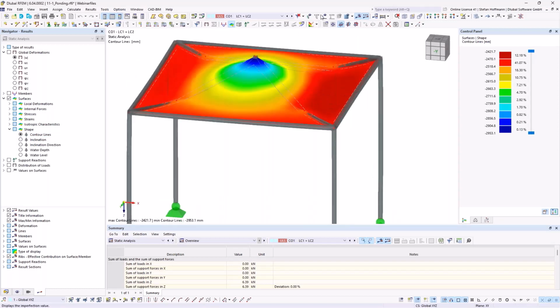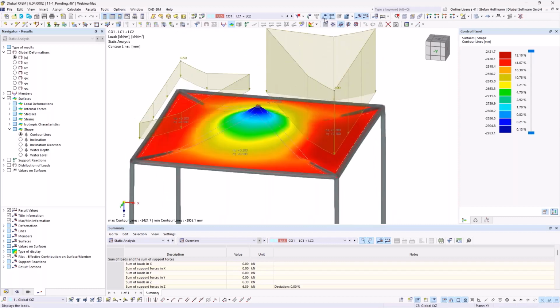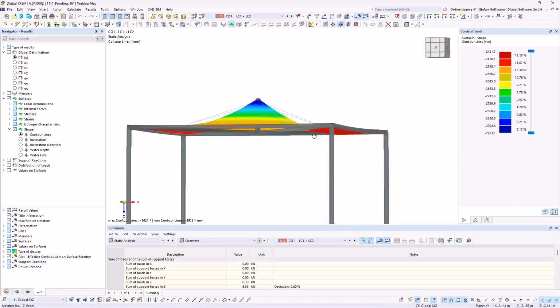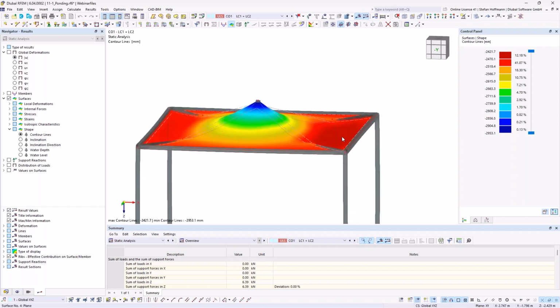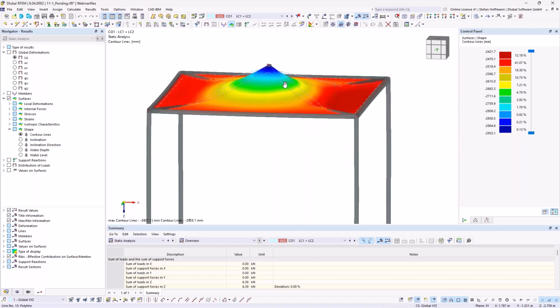So it's the pre-stress I put in my structure. And then there is, let's call it, the heavy vertical load. And as you can see, my membrane will, due to the effect that the load is higher than my pre-stress, bend down. And the highest point of my members is 2.50 meters, and my membrane will be about 8 centimeters below this point. So this is most likely the lowest point, and this is an available point for water to accumulate.